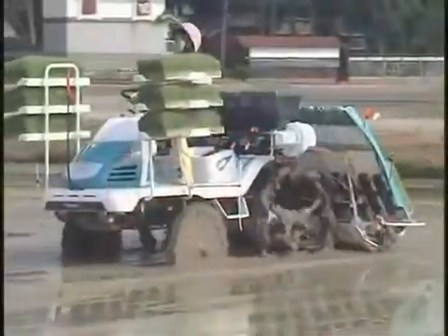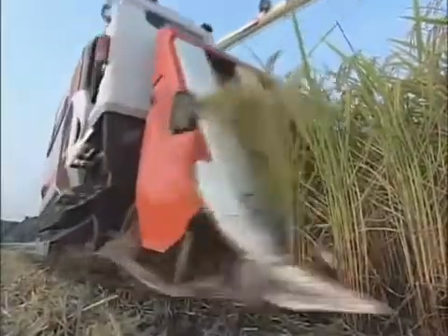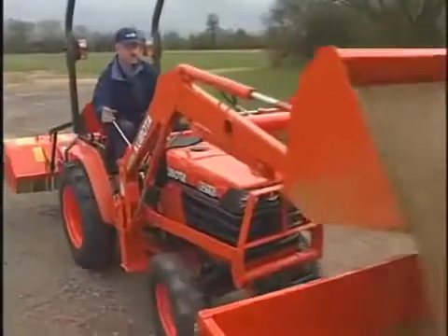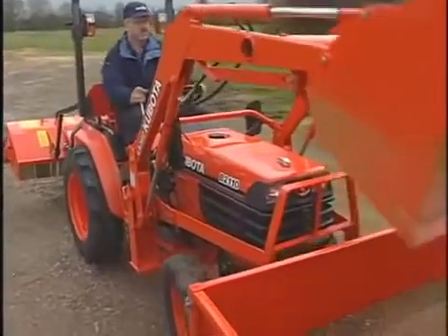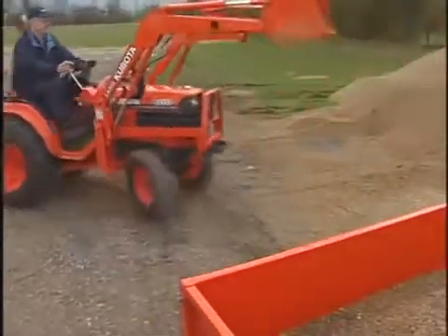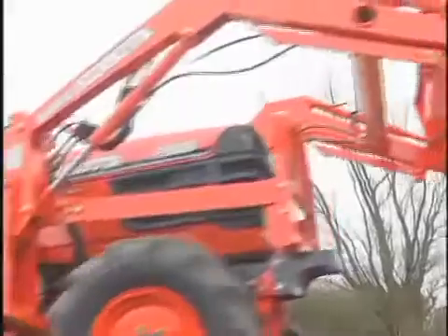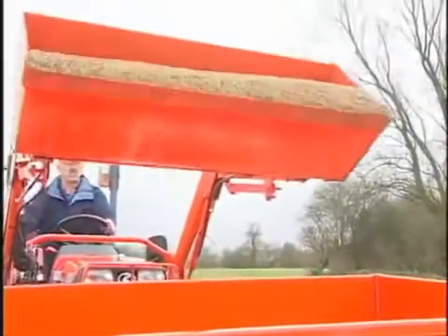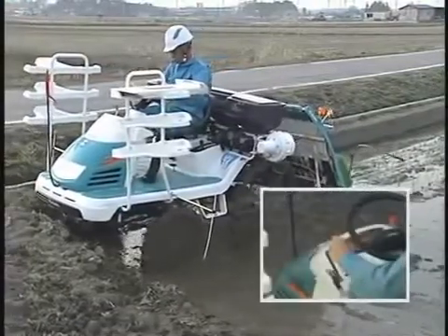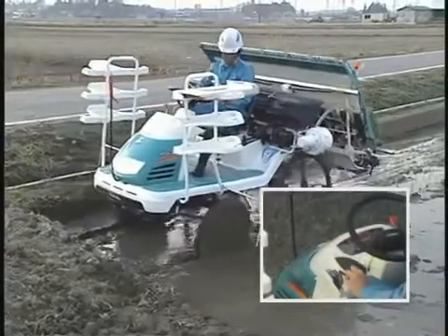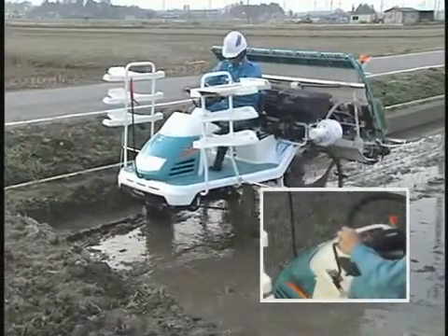In the field of agricultural machinery, work efficiency has become a top priority. Efficiency can be enhanced through easier machine operation, such as by using an HST or hydrostatic transmission, which dramatically improves ease of operation by enabling an operator to change from forward to reverse and to change speeds using just a single lever or pedal with no need to operate a clutch.